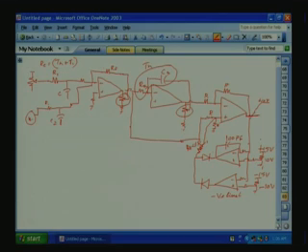Now, let us say the output is going negative, minus 10 volt. So, what happens? This is already more negative than this minus 10. So, minus to minus 10 will come here, and this will immediately go here and the output will be raised to minus 10 volt. If it goes below this, it will raise it. As I told you, we are using a P controller here to control the output.